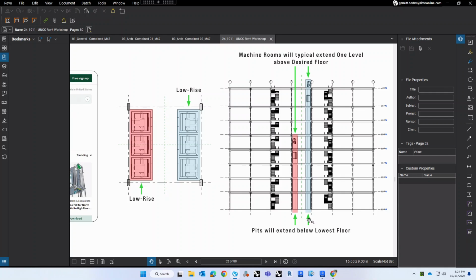Two things that you have to make sure of: at the base of your elevators, you're going to have a pit. When an elevator goes down to the ground floor, it needs to be level with the floor slab. But the elevator is not flat on the bottom. It has a ton of equipment, and also underneath, separate from the elevator, is all the equipment that conveys it, as well as a bunch of safety springs and all that stuff at the base.